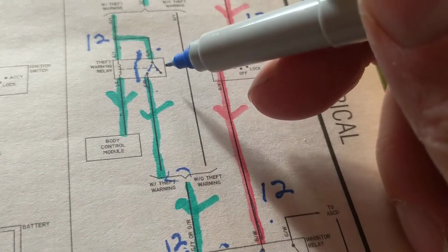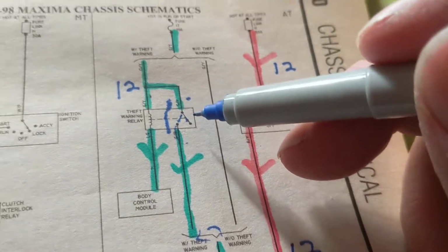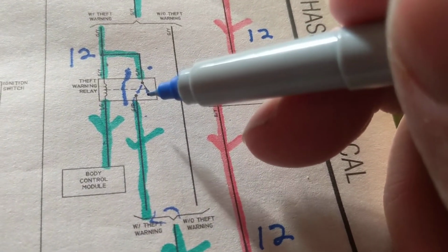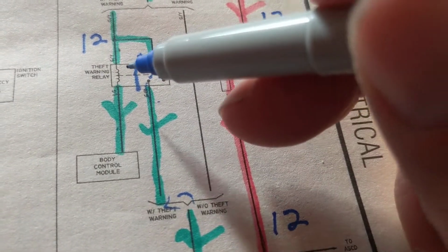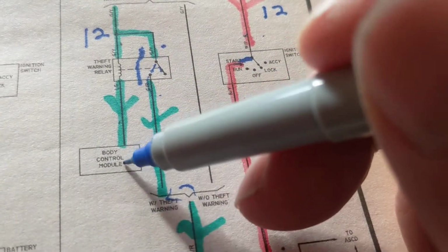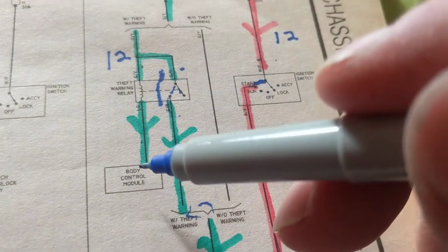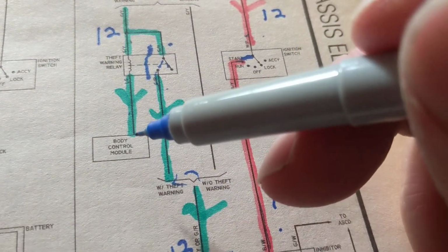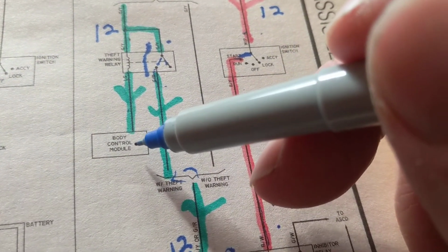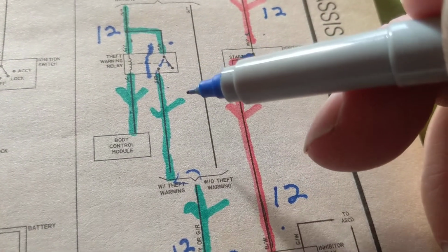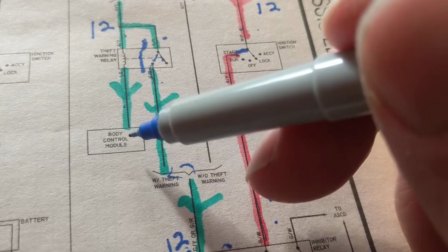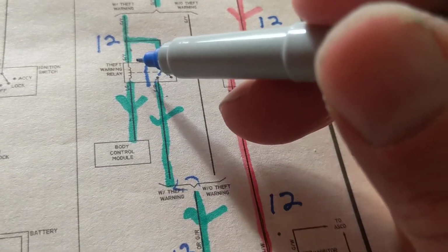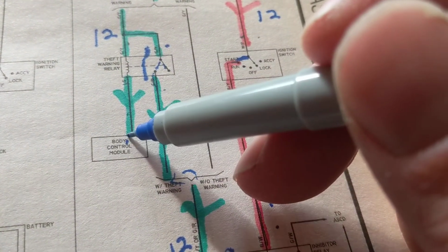Therefore, I come back over here and I say, okay, maybe this has not been activated. Okay, but what would cause this not to activate? This. Maybe the BCM is the problem besides the fuse. Oh, wow. So the module can cause a domino effect. If the BCM is not complying the way it's supposed to, this will not work.